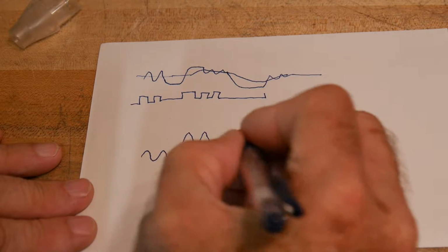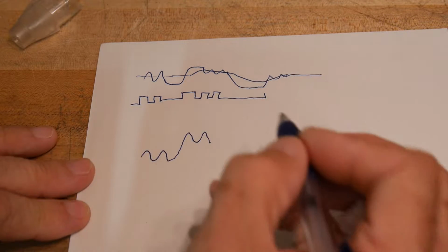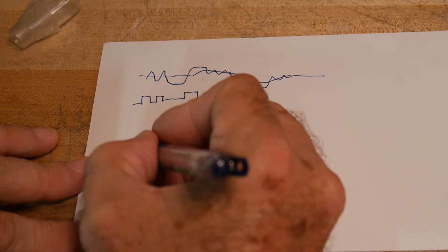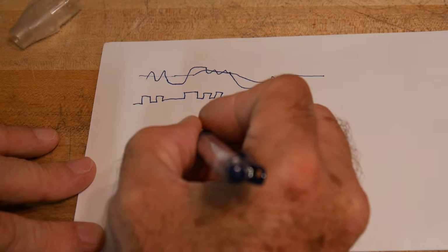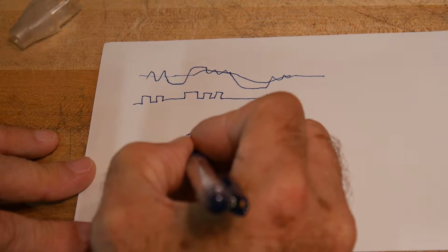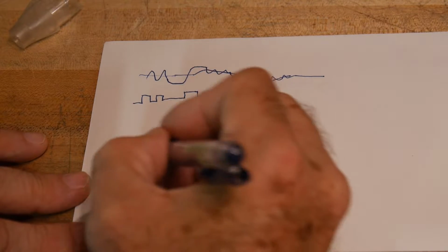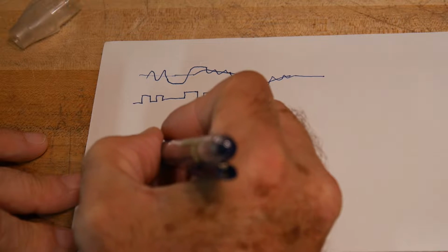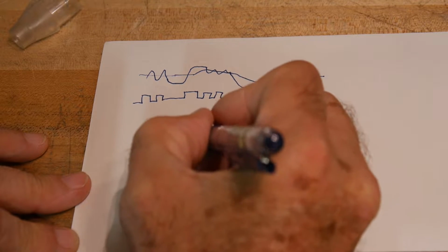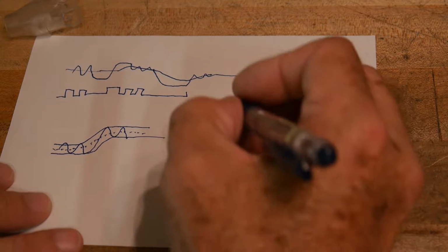If we wanted to have a threshold that made it through this thing, if we put in a circuit that's a peak detector, we could have a peak detector that sort of follows the peak, and we could have a negative peak detector that sort of follows the negative peak. And then we could say, okay, well, we're going to take a 50% threshold between those two peak detectors and run that into a comparator. So we can do that.